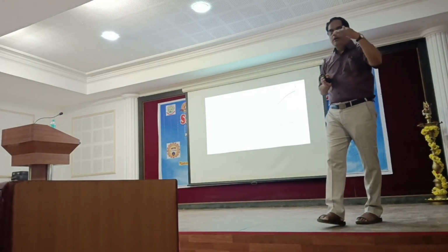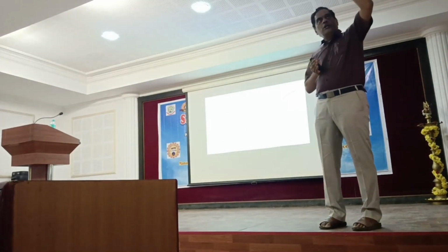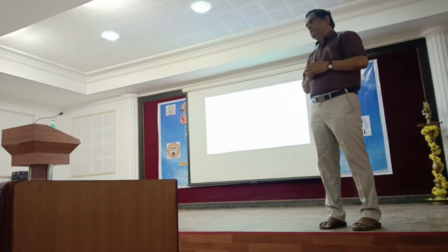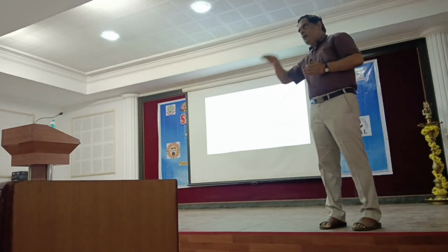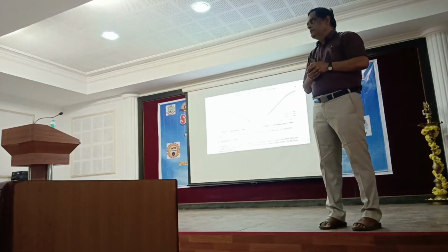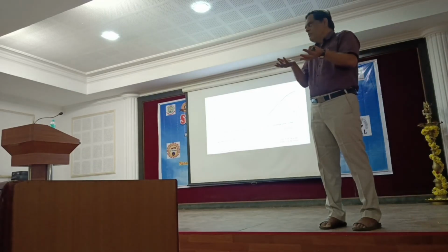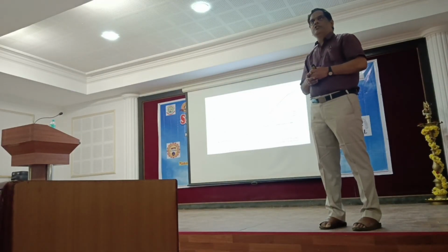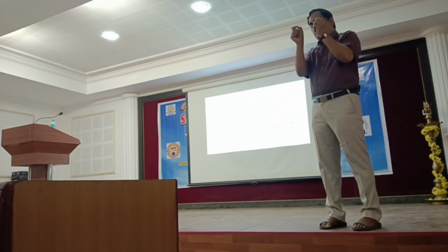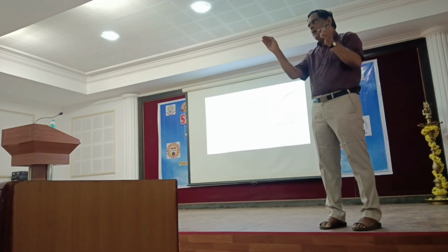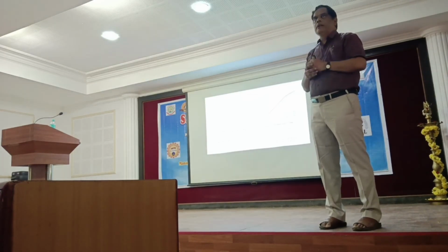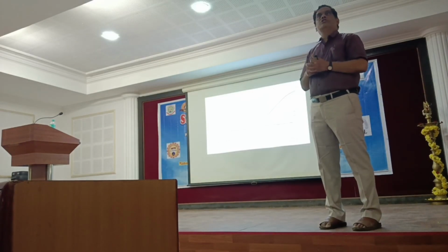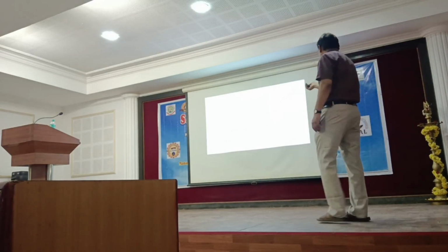That's why we talk about shallow discharge and slope discharge. Which one is better? Shallow discharge is obviously good, but sometimes when you apply quick braking, you always go for very rapid discharging or charging. You should know what the discharge profile is, shallow profile or slope profile. Depending upon that, your SOC is going to change as a function of time. All such things you can impose.